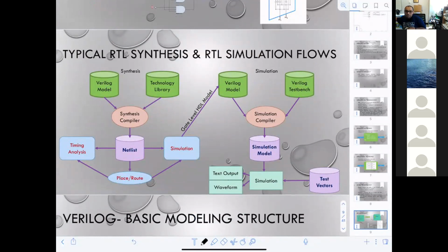When we write the code on the FPGA, is it similar to how assembly and C work? No. I will come back to this later. Verilog, or a hardware description language, is a parallel language. So debugging it is quite hard compared to debugging a sequential language like C or assembly, where you execute instructions, go to another instruction, and back to another. In Verilog, you can find a bunch of them running in parallel, doing something different.